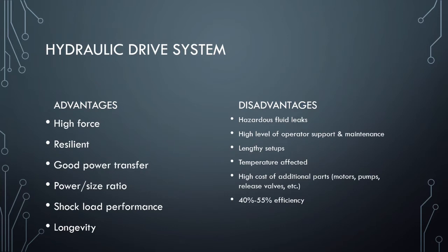Lastly, we'll take a more detailed look at the advantages and disadvantages of a hydraulic drive system compared to the electronic and the pneumatic drive systems. These systems certainly have the highest force, or the highest power, out of any drive system. The hydraulic fluid really gives them a lot of power. They're also able to be really resilient. So if there's a lot of shock and vibration happening in the environment, maybe it's a really unstable environment, these systems can weather it really well.